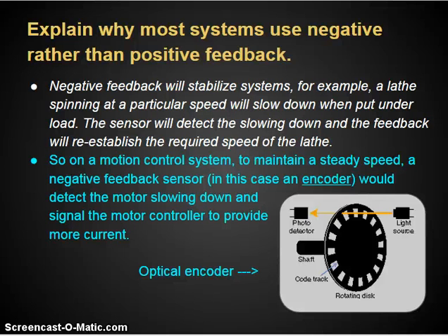That is, negative feedback is simply if it's not doing what it should be doing. So in the example of the oven again, if the temperature is not at 350 degrees, that's a negative feedback. It doesn't have a positive feedback. It just relies on when it's not doing what it should be doing. Like the encoder on the control system. If the motor is not spinning at the right speed, it then will apply more current or slow down other motors to match its speed.